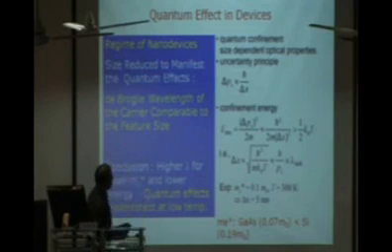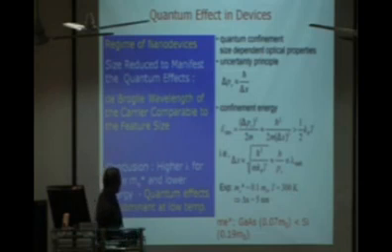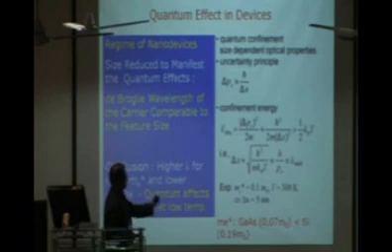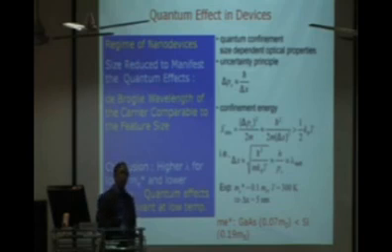If you take the effective mass of an electron in a semiconductor system as about 0.1 of the free electron mass, and the temperature as room temperature, 300 K, the delta X we can get is about 5 nanometer. We can say that if you have a material, a quantum dot, or a size less than 5 nanometer, we are supposed to see the so-called quantization of energy.